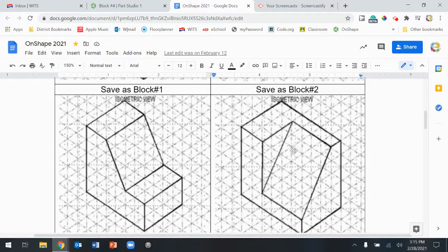To use the subtractive method, we have to know the total length of the object, which this one right here is 6 boxes, so that's going to equal 1.5 inches. We need to know the total width of the object. Here it is right here. It is 4 boxes, so that's 1 inch. And we need to know the total height of the object, which is 5 boxes, making it 1.25 inches. So what we have to do is draw that whole big rectangle. It's going to be, again, a rectangle that's 1.5 by 1 by 1.25.